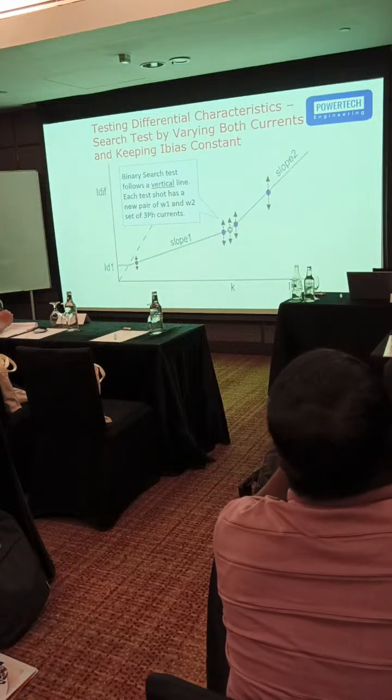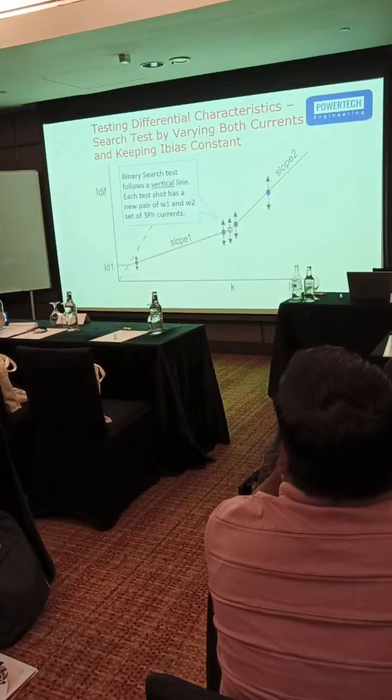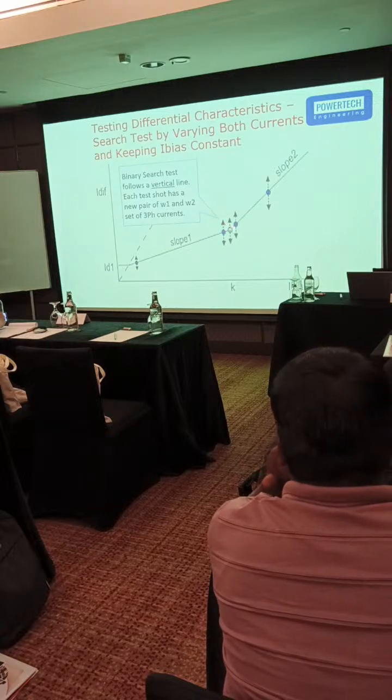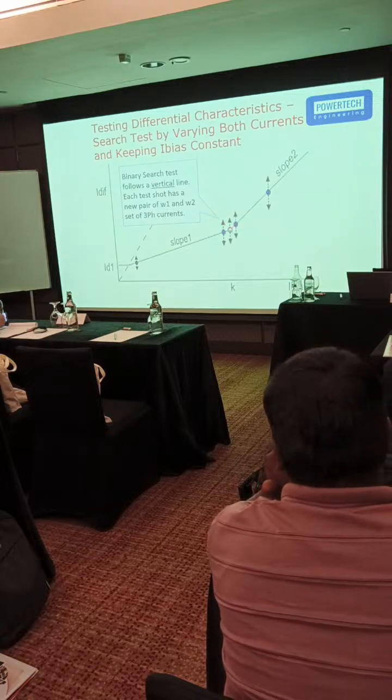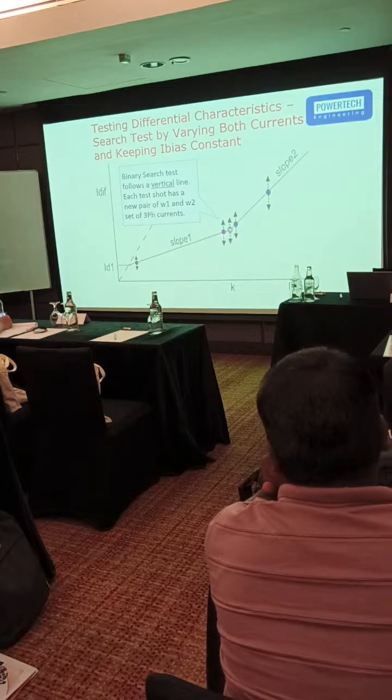When it tripped, they reduce the current again and move this point lower towards the non-operating region. If the relay is still tripping, then again they reduce the current, so that the exact boundary point can be found. Once they find the exact point, there is a pass/fail indication that the relay passed the condition.